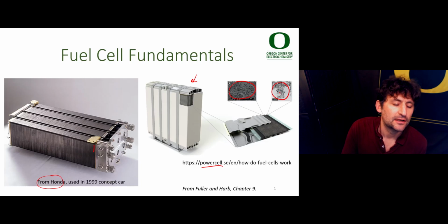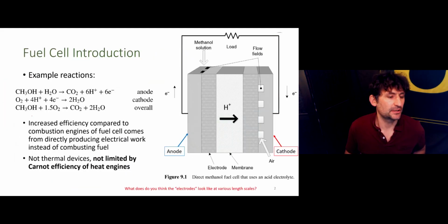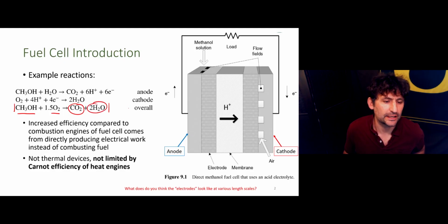their performance parameters. Fundamentally, a fuel cell is any electrochemical device that drives an overall downhill electrochemical reaction involving a fuel and oxygen to generate two products that have lower free energy. This leads to a reaction that you can extract usable work out of. This reaction is identical to the reaction you would write for the combustion of methanol, except in this case, we're doing that combustion reaction separated in space.